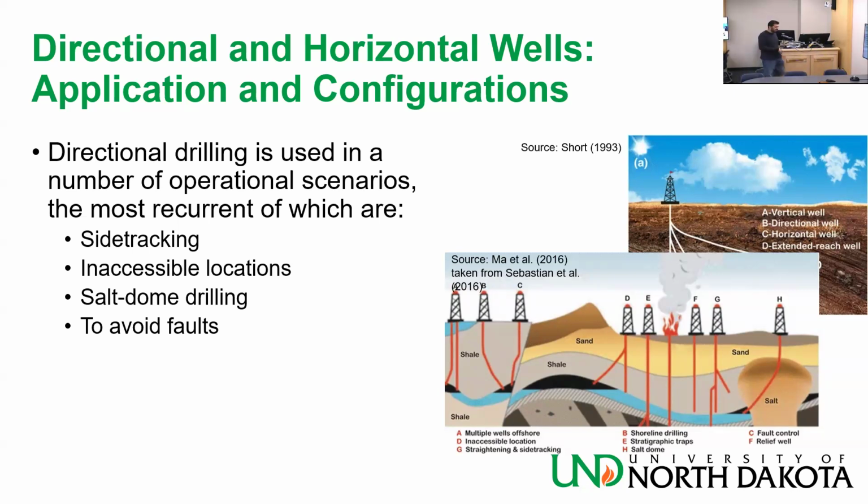The directional driller got very excited and forgot that there is this lag time. The cuttings coming to the surface are not from the depth that your bit is at right now. It takes about an hour for the cuttings during normal drilling operations to make it to the surface, so we need to take account of that. By the time the geologist figures out that we passed through a fault, you are already in it, or you already passed through.